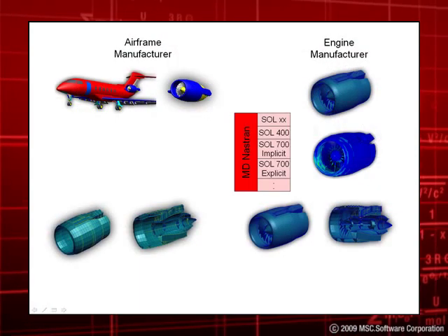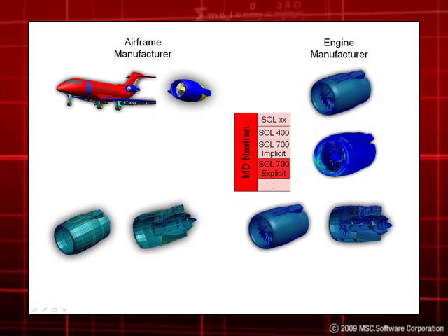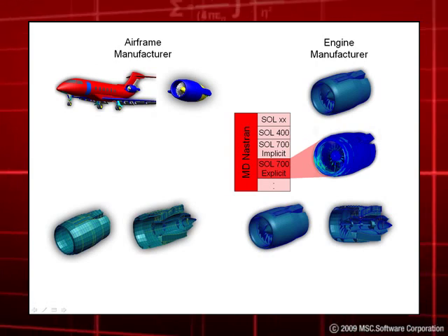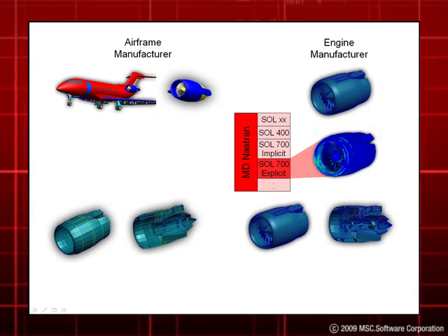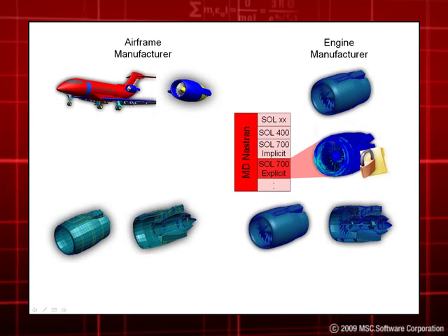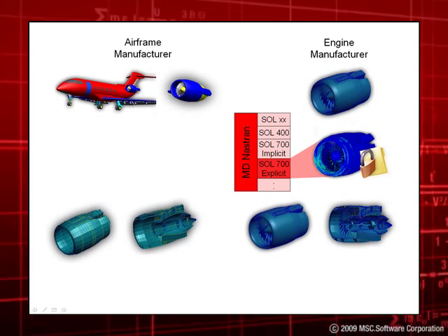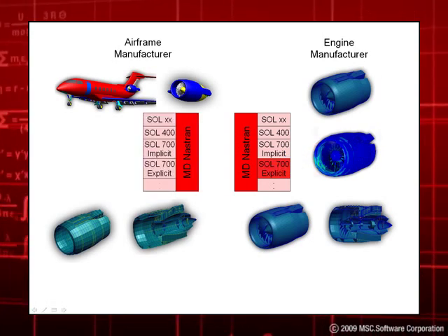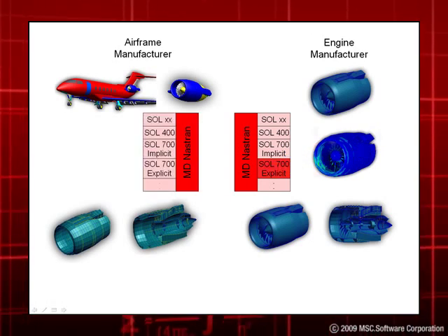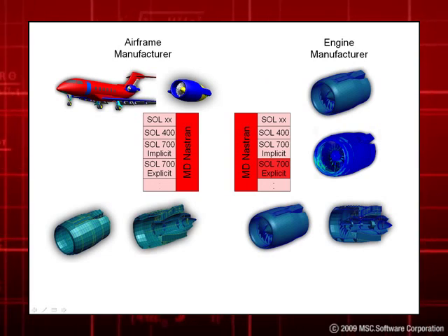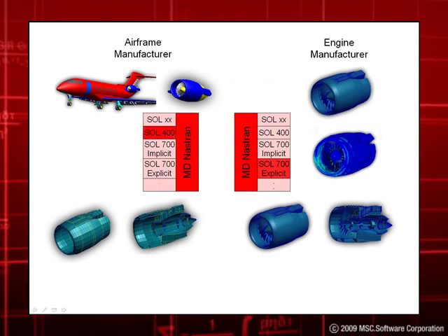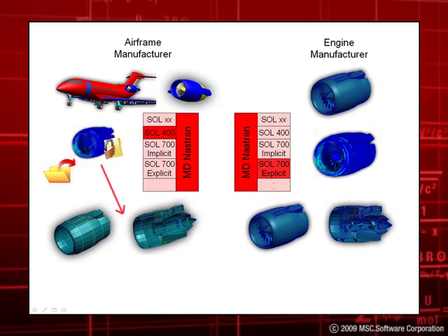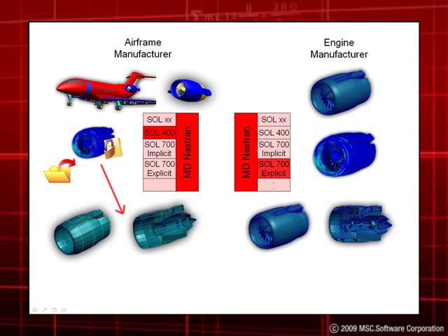This methodology allows the engine manufacturers to use MSC Nastran Solution 700 explicit solver to save the realistic loads, which could be in millions, in a Nastran database, maintaining the necessary fidelity without exposing the confidential model information and IP copyrights. Those loads are then passed on to the airframe companies in Nastran database format. The airframe companies then use MD Nastran Solution 400 implicit solver to read in the loads onto the rotor dynamics model, which is much coarser than the fan blade out model.